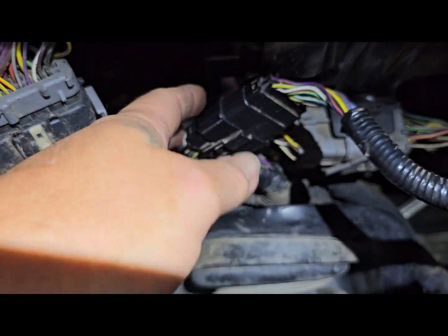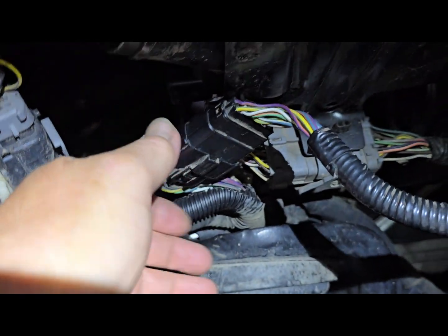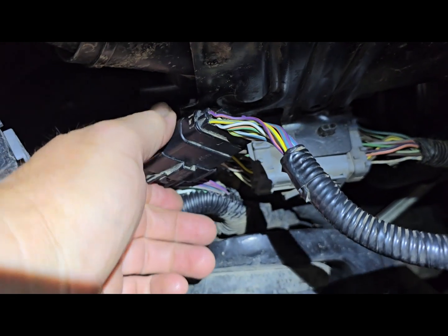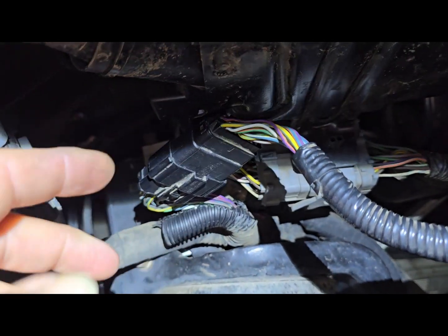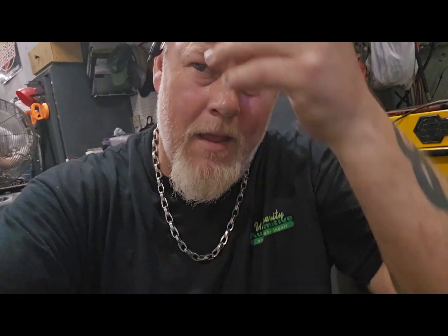So this is what happened, and this is why I had a lot of frustration: this connector was backed off. Because this connector was backed off, it caused me to have a lot of codes. And it also led to, when I disconnected the ABS module, there was no change to the network because that connector was disconnected. So I had to jump through hoops, all because they had disconnected that connector. Connector's connected, ABS module is disconnected, we have communication, everything is working. It needs an ABS module.